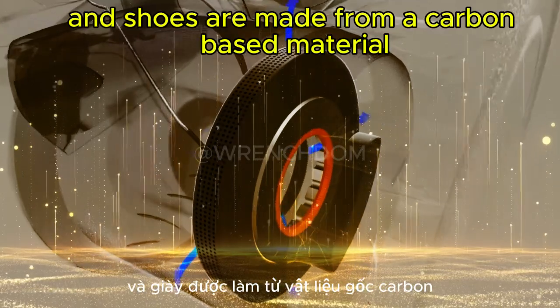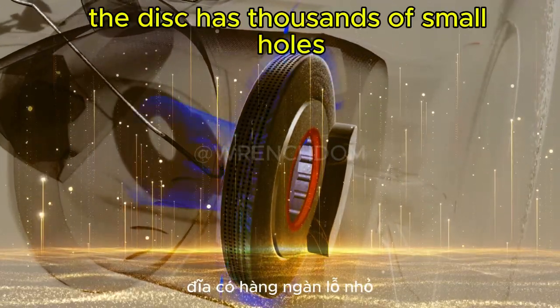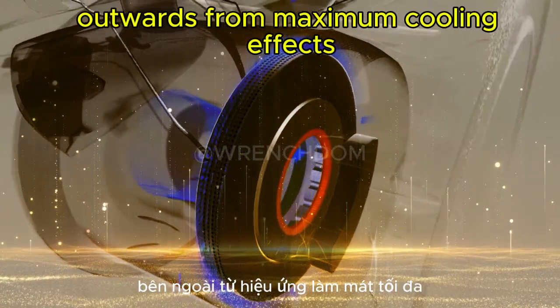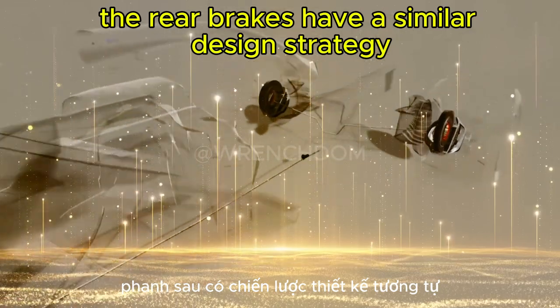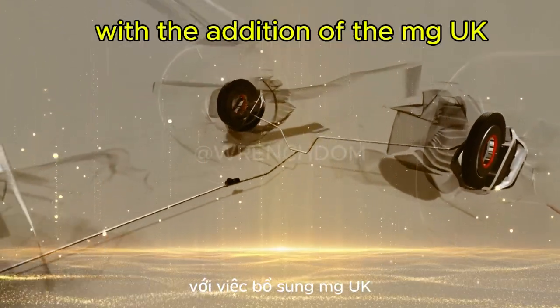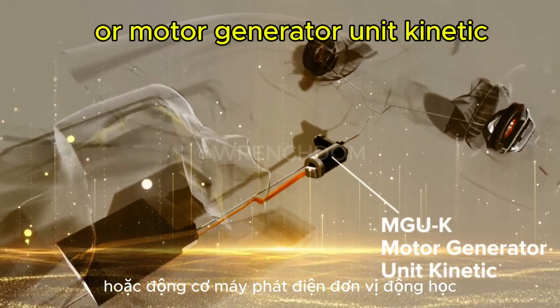The brake discs and shoes are made from a carbon-based material. The disc has thousands of small holes extending from the center outwards for maximum cooling effect. The rear brakes have a similar design strategy, but have become smaller in recent years with the addition of the MGU-K, or Motor Generator Unit Kinetic.